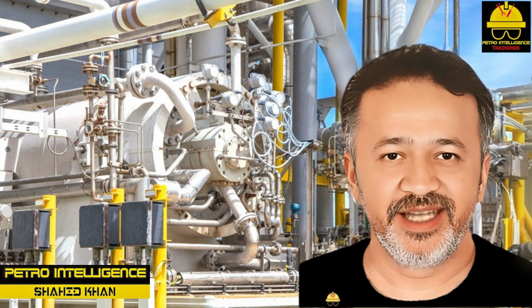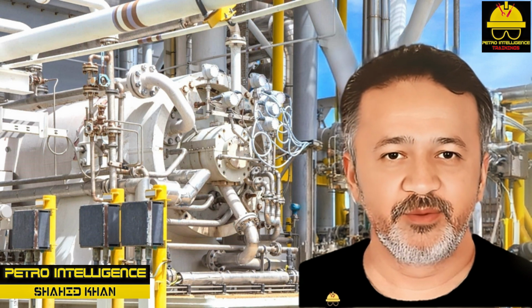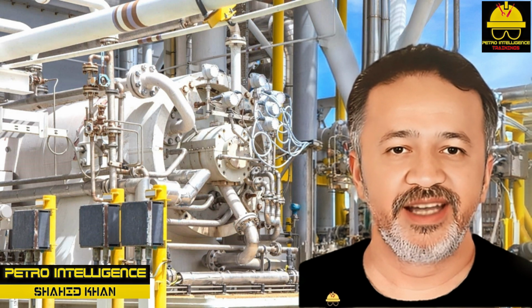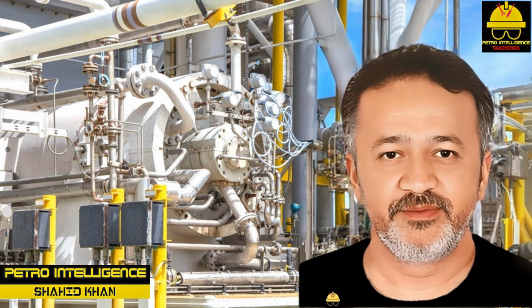Another feature associated with the rotary screw compressor is its ability to be used as a vacuum device. This system is designed to handle 500 to 10,000 CFM on the suction side and to pull a vacuum between 5 and 25 inches of mercury.